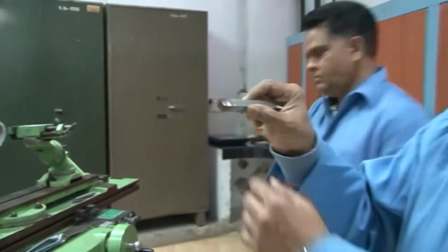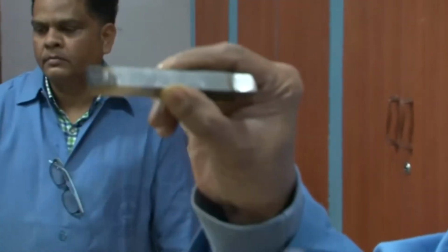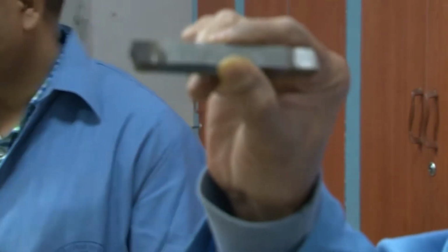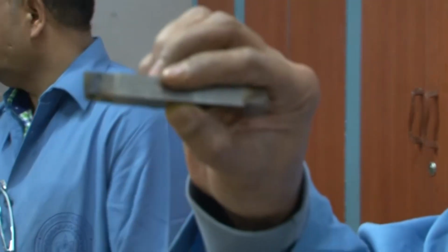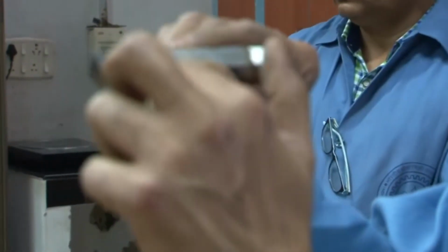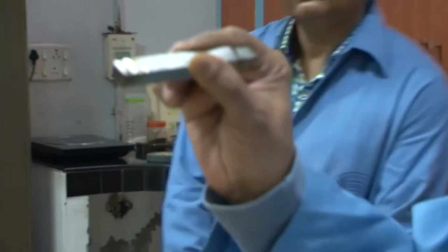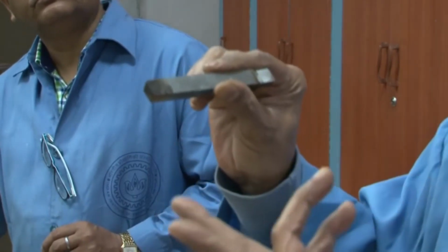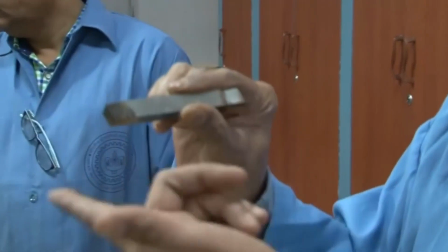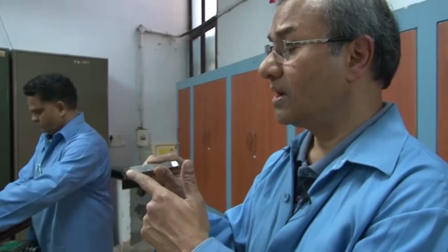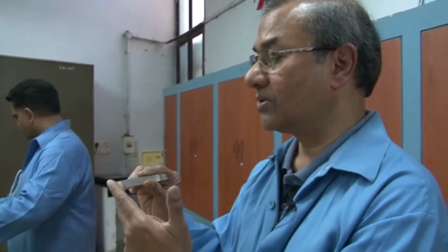And now, if you concentrate, this looks a little burnt, because at a high temperature there is a burning tendency, and that is why this is hot actually. I am holding it, but it is hot, and this color came because of the burning of the surface to a certain extent. However, this does not cause thermal distortion in the vicinity of the tool. However, if it happens at a very high temperature, then it may be distorted, meaning that other angles which are there may be distorted. So, that has to be protected.